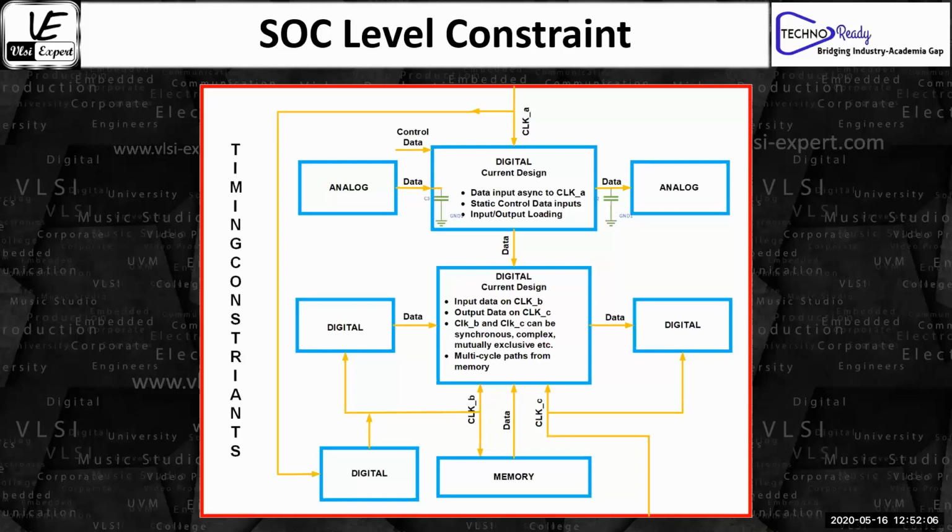So it's just about where exactly you're sitting and what information you have. If you can figure out the relationship, if you can ask the top level people, "Okay, I need a relationship between clock A and clock B," and the top level person gives you that relationship, then it is very easy for you to design or make the circuit inside this digital block.